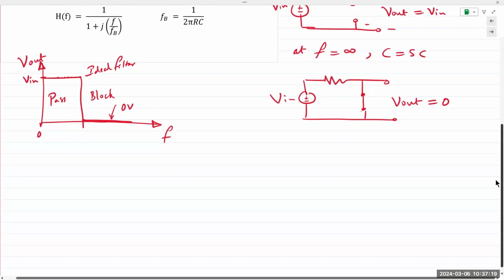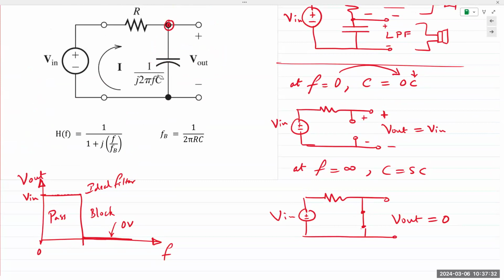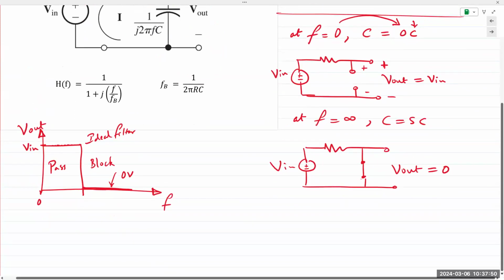Anyway, coming back to the quantitative analysis. We can analyze this circuit in the exact same manner that we did for resistors in chapters 1 and 2. It's a series connection, right? And so a series connection will have the same current I flowing through each component. And these are all phasors, complex quantities. So the same current I flows through the entire circuit because it's a series connection.